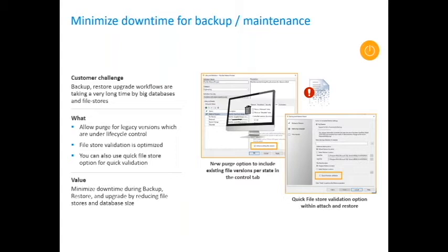And they've added something to help. If you turn on certain lifecycle states, this will actually allow it to go back and look for older, historical versions and allow you to purge those as well. What purging means is, let's say you check in a file 25 times over the course of its life. Over 5 years, maybe the initial design, you checked it in 5 times and released it.